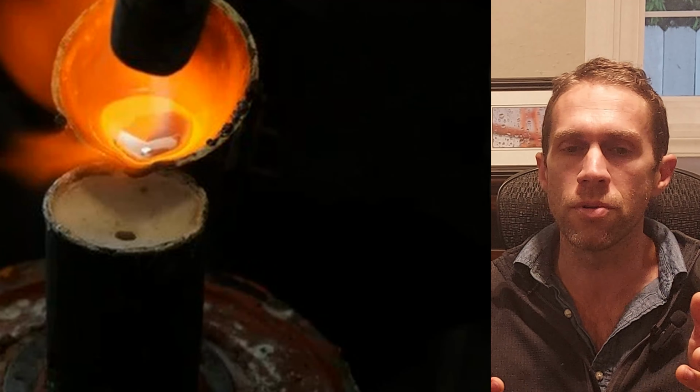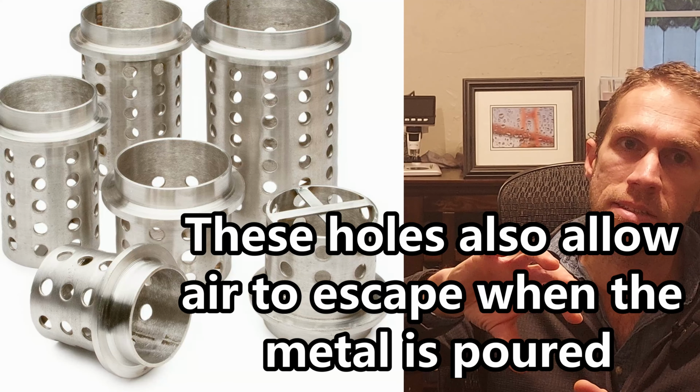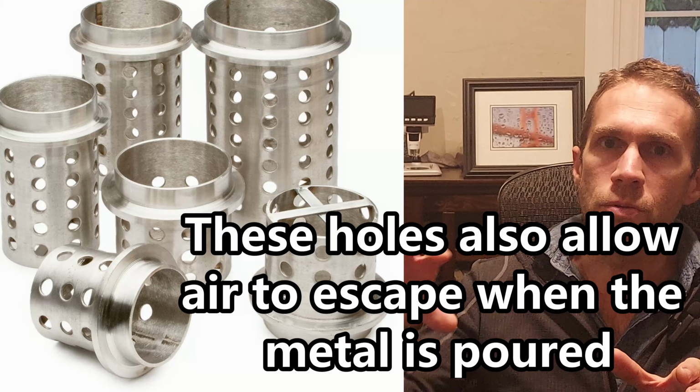The reason it's porous is that when you pour the molten metal into the flask, that metal will airlock if it doesn't have any way to push the air that is in the mold out. So that air needs to be able to escape through the investment material, which is why it's porous at a very small level, like a microscopic level.